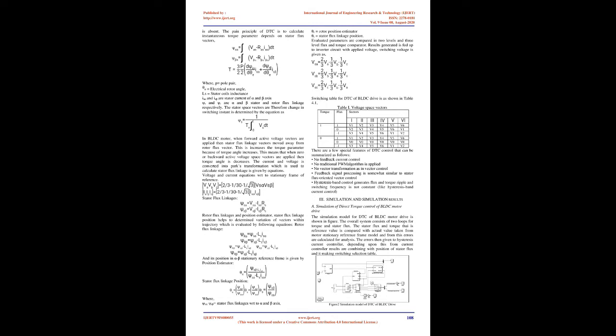For energy saving in industry, there is an increase in use of variable speed drives. Initially, direct current machines are controlled by the decoupled nature of flux and torque, then field-oriented control and DTC methods were developed. Also, these methods are then used for control of AC machines. In field-oriented control, there is a current controller, whereas DTC needs to know just the sector in which the stator flux linkage space vector lies, rather than the exact position of the vectors.